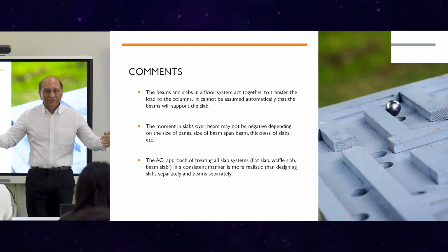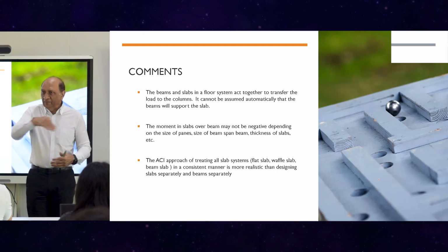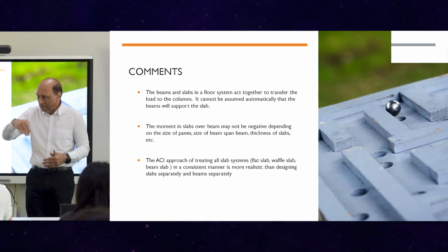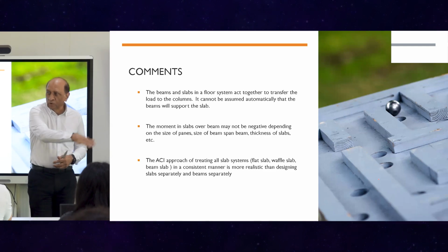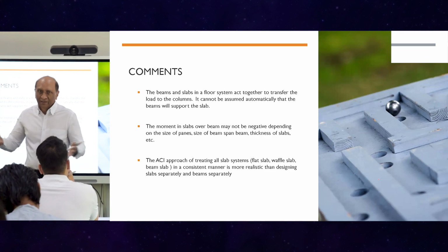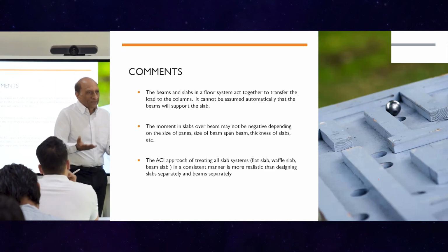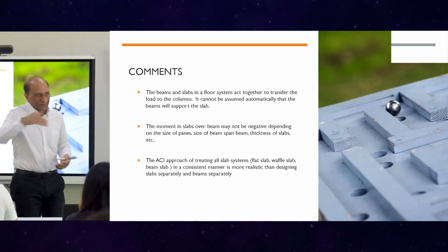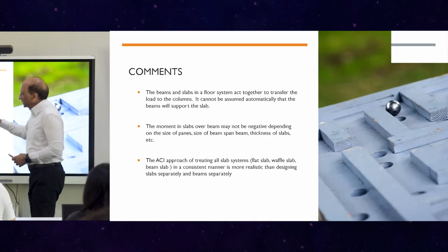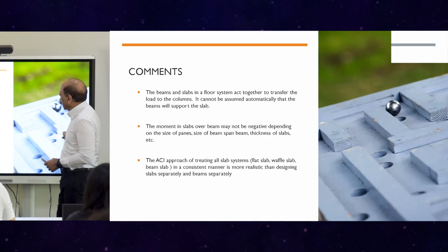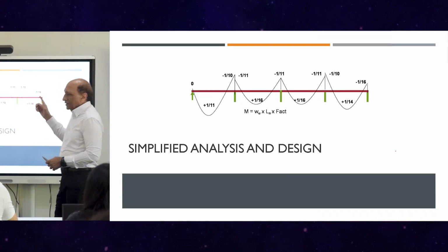So if through post-tensioning, we can ensure that the slab will not deflect in one direction, we can create an artificial support and the slab will then go over it. Because in post-tensioning, you can post-tension in such a way that you lift up the slab to become straight. No deflection. Anyway, so that's the summary of this discussion.